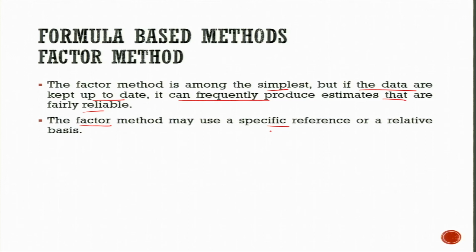For example, in an activity, if 400 hours is taken in printing for a specific product, then we can say that a printer with 2 nozzle heads would take 200 hours, something like that. This is a factor based method. So, I would say 400 hours of a product produced divided by 2 nozzles or nozzle heads gives us 200 hours per piece, if we increase the number of nozzles from 1 to 2.